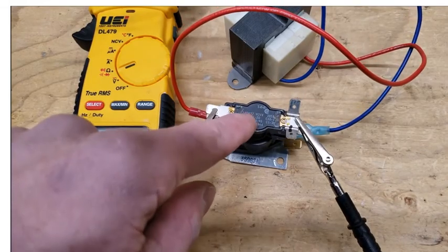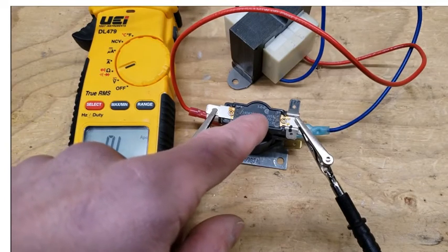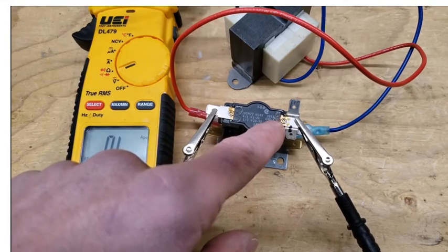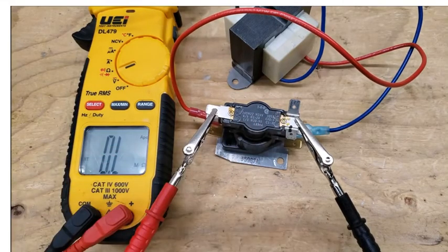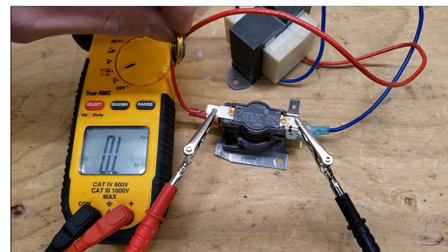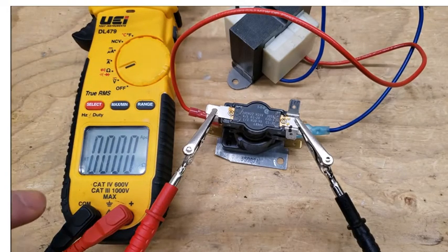So over here at the top you see 4 to 5. It takes 1 to 20 seconds for those contacts to close, and then it takes 40 seconds to 120 seconds for those set of contacts to go ahead and open back up again. So here we go. So what's happening now is that little pane heater is heating up the thermo disc. So it really shouldn't take long, and there you go. So we're reading 0 ohms of resistance across the contacts.